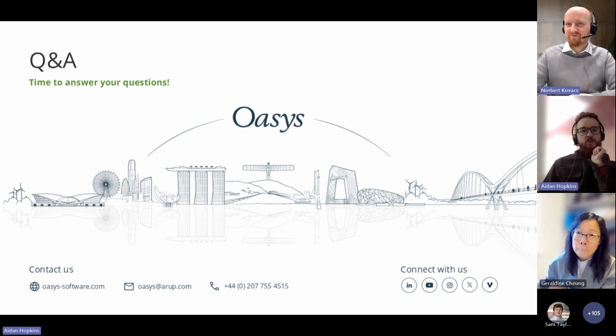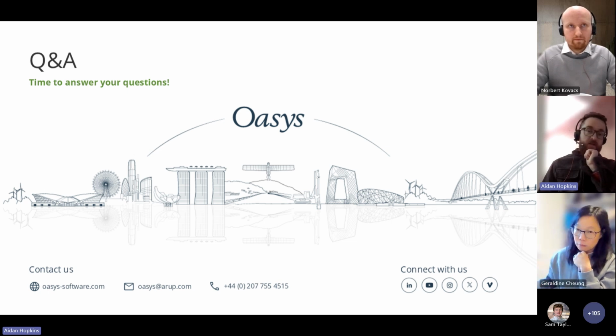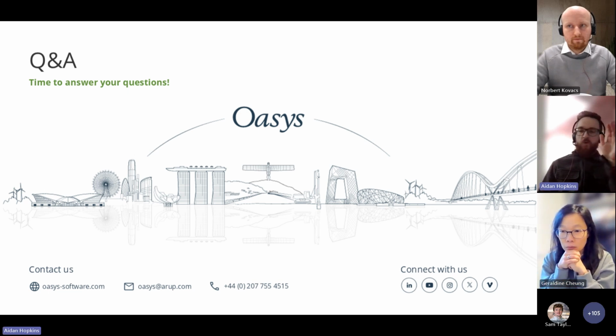Okay, thank you. I'll just quickly add to that, that there's also the corner stiffening for shafts that I'm sure Geraldine and Sam used for smoothing if we're going around the corners. So where we do have discontinuous results, that can be pretty useful. I've often used that in conjunction with 2D and 3D, to give us an idea of how that smoothing might happen, and then we can adopt XDisp when we really want to do the building and utility impact assessment to then match our corners, basically. So I just wanted to add that.